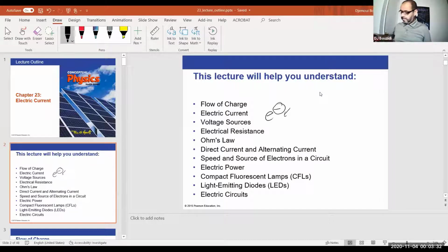I have actually another device in here, which is even better than that. This one can measure voltages, resistances in ohms, frequencies, and capacitors. So it measures a lot of things. It can measure currents also, both in AC and DC format, in small values or higher values. Again, you always have the ground in the black one. For the voltage and anything else, you use this side. For the currents only, you use this side, depending on the value of the current, if it's too strong or too weak. This is a multimeter, okay?